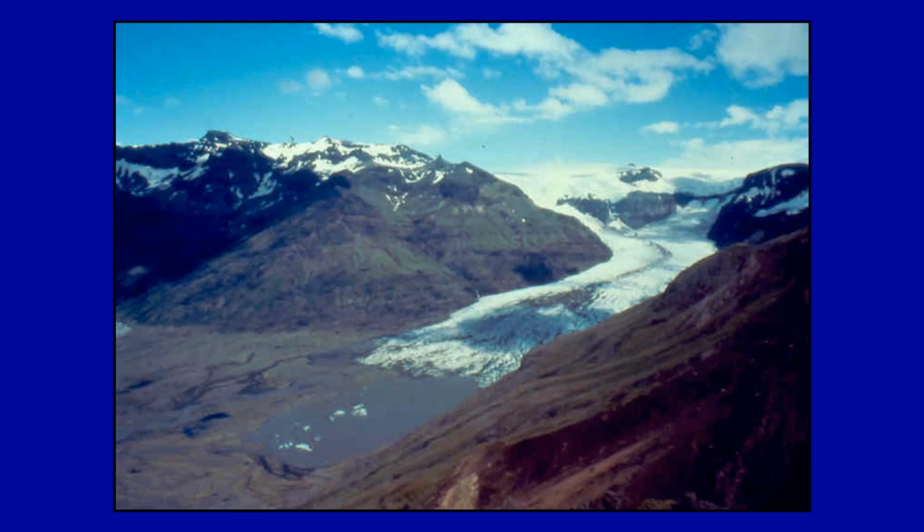And around kettle holes, the potential for sand and gravel deposition with what would appear to be water developing transmissive sediments may in fact be possible. An example again of a glacier in retreat. Please notice on either side, as a glacier retreats, it shrinks in from the sides and down from the top, but in fact you can get coarse sand and gravel deposits on the side of the valley.